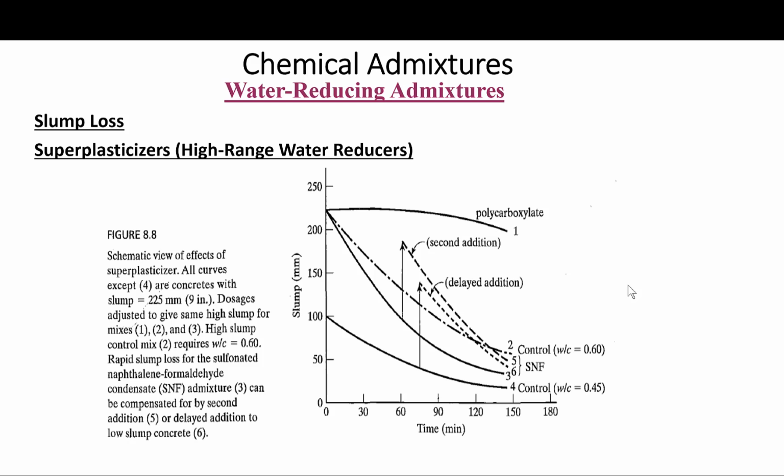Okay, that's what I have to say about this. Do not just do it at will. The retempering with water should never be done, and the incremental addition or the delayed addition of the admixture should be planned and should be decided by the ready mix supplier or the material manufacturer.